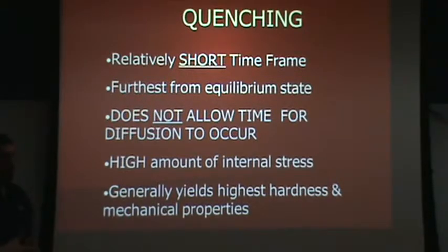And so it's quite important that as we look at what we're going to quench, we pay attention to the geometry and we're careful, especially with corners, especially inside corners. Sharp inside corners are stress concentrators, or stress magnifiers, especially during quenching. And so we have to be careful that we avoid having those during the quenching operation. The part may need them, but they may have to be machined in afterwards.